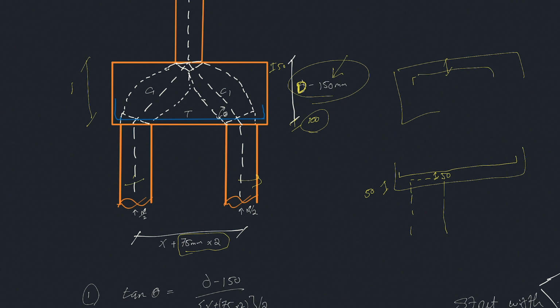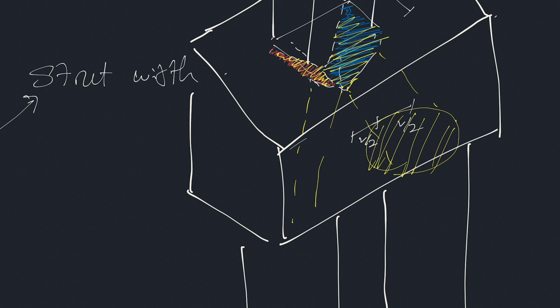Struts don't have to be perfect. They follow the shape of the bearing element, because that is the shape of your column, that is the shape of the pile. At the top they're gonna follow the shape of the column, and at the bottom they're gonna follow the shape of the pile, and you take the worst one between the two. Don't worry about it being perfect size, because it's not perfect, just the concrete will start diverging the stresses straight away in compression.